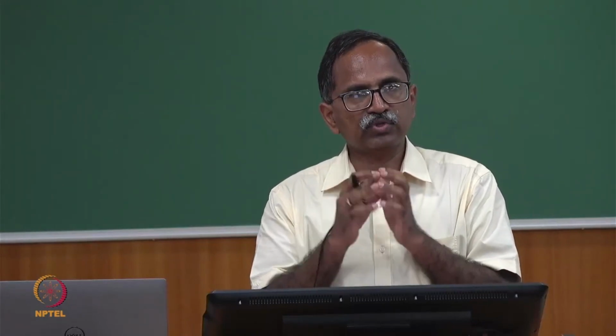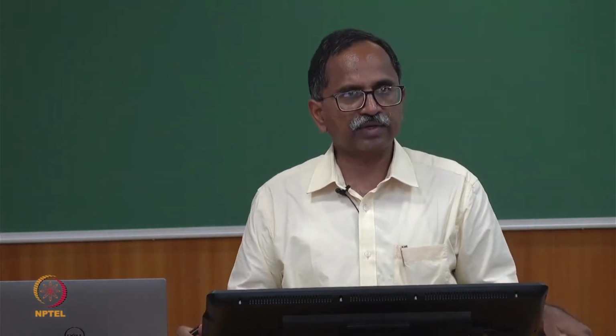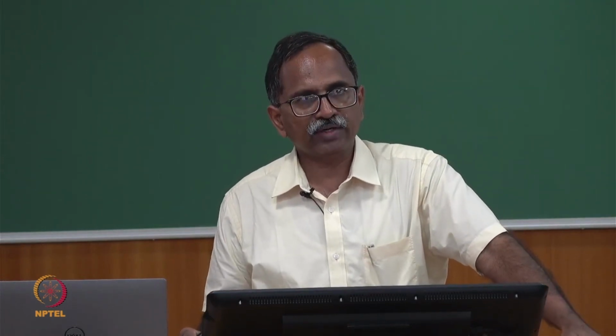Okay, so the positions of the nodes or nodal lines in a two-dimensional vibratory structure are important from this practical viewpoint, that I would like to locate any additional mountings there.